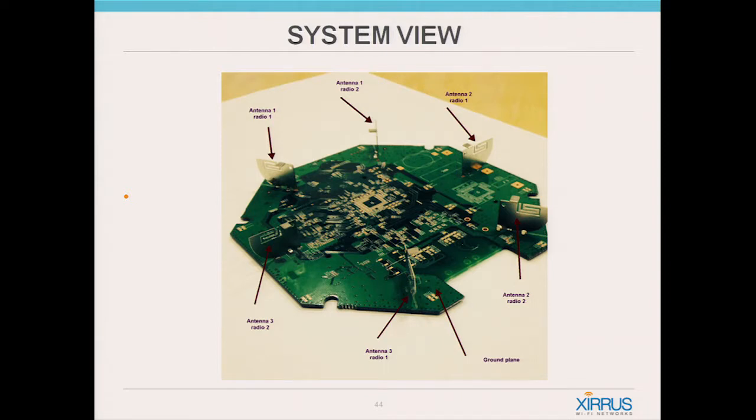And the beauty of what I'm doing here is that I'm creating what we call an interleave arrangement. So I'm taking that antenna, and that antenna, every other antenna, this, that, and that, connected to one radio, and the other group to another radio.